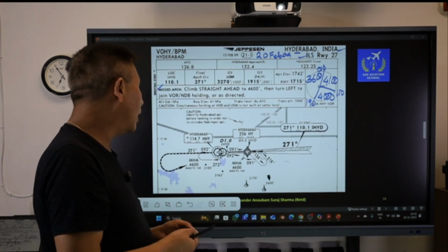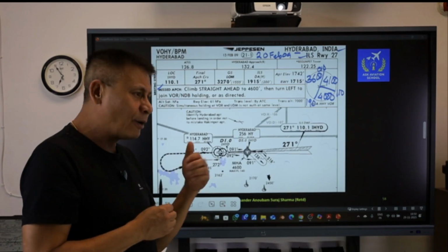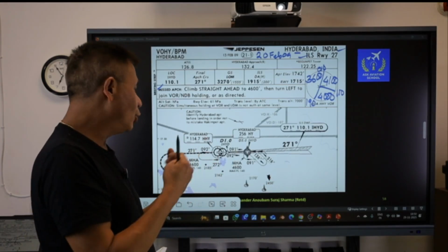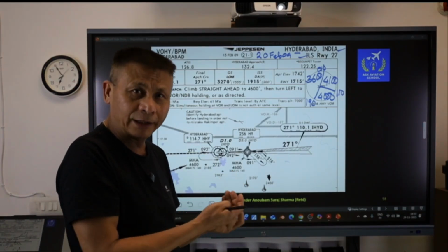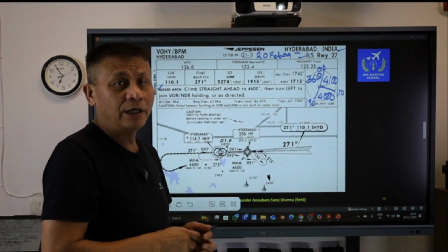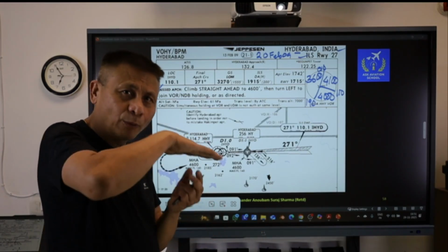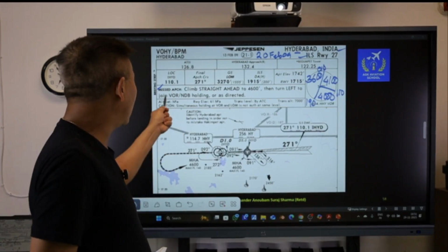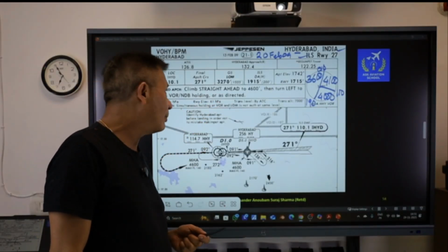Depending upon the instrument approach procedure you carry out, the number of lightings which you are supposed to see is different. If you are able to see and identify these lightings or the markings, then you can continue and land. However, if you are unable to see these lightings, then I am supposed to carry out a go around, which is known as the misapproach, and the procedure which I am going to be following is what we call a misapproach procedure.